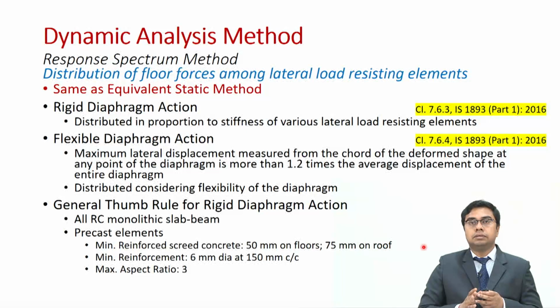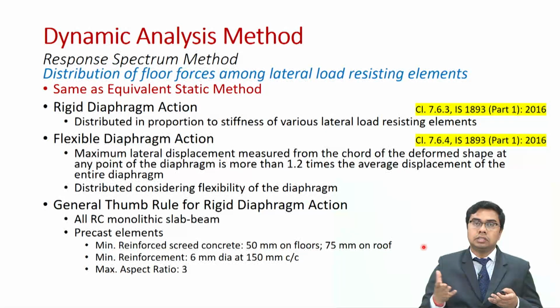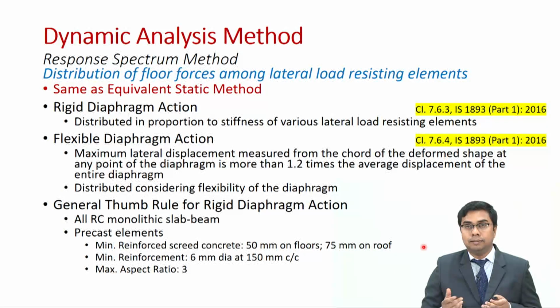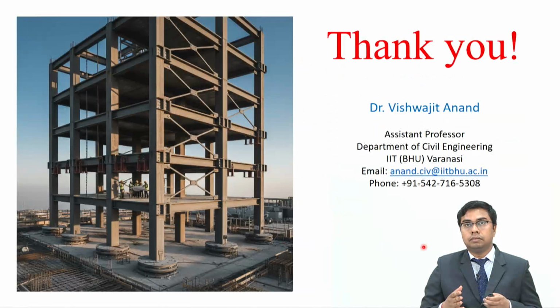So, in this class, summarizing, we have looked at the dynamic analysis method, particularly the response spectrum method, and how the different steps are executed. We start with determination of the dynamic properties of the building, then we move to estimate the design seismic load considering all the different modes, then we move further to distribute these floor forces among various lateral load resisting elements. In the next class, we will illustrate the same using an example problem. Thank you.